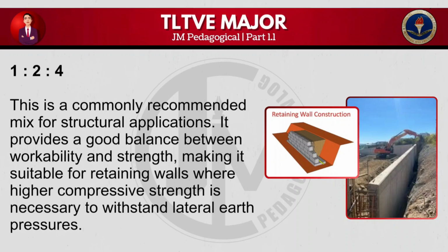This is a commonly recommended mix for structural applications. It provides a good balance between workability and strength, making it suitable for retaining walls where higher compressive strength is necessary to withstand lateral earth pressures.